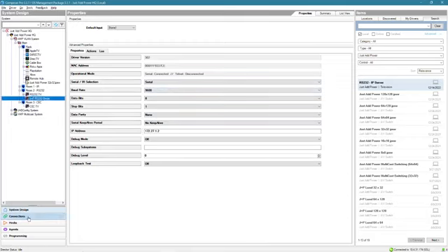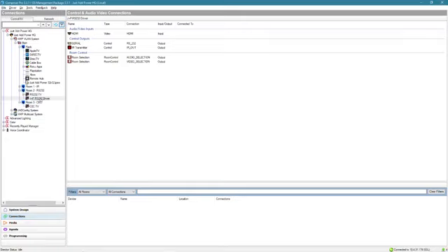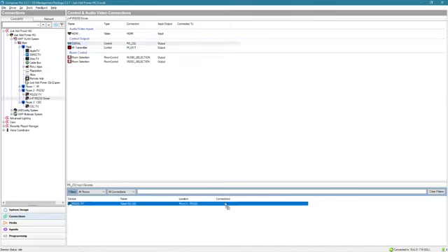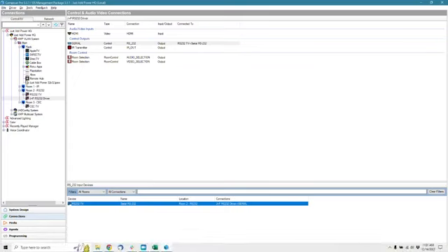The last thing we have to do is go into our connections. And we're not using a serial port on the Control4 processor. We're using the serial port on the Just Add Power driver. We're going to connect it to the serial port on the TV. This ensures that when Control4 sends serial commands, it's sending them out the IP port to the Just Add Power device and not one of the Control4 processor's serial ports if you have them. And that's RS-232. It's done.